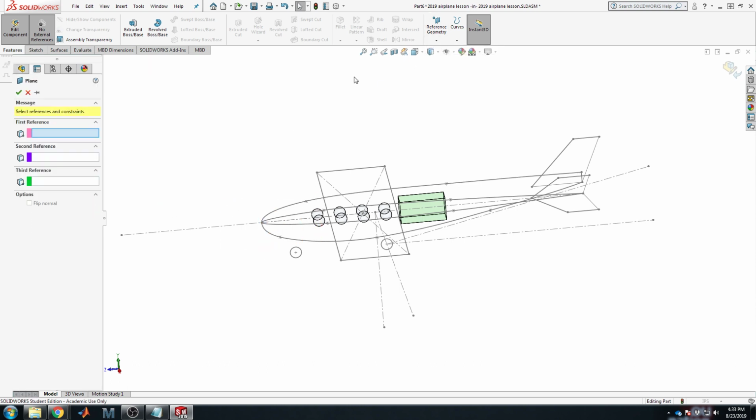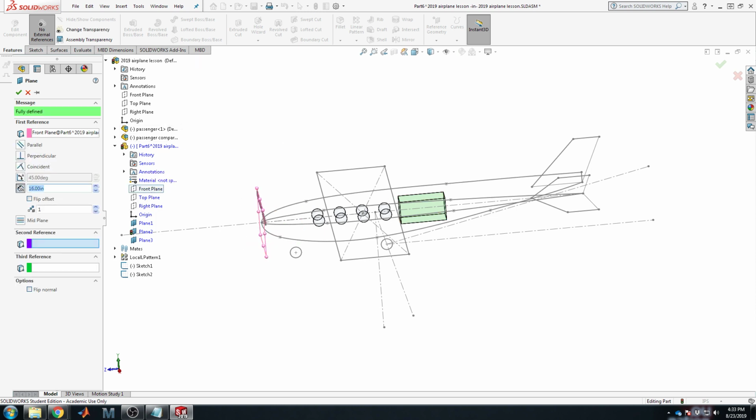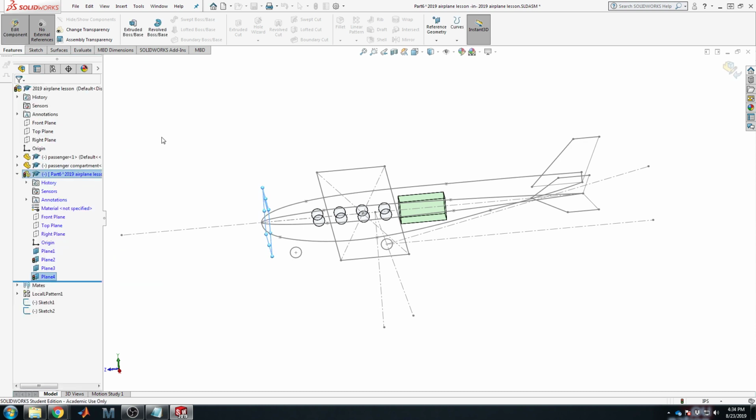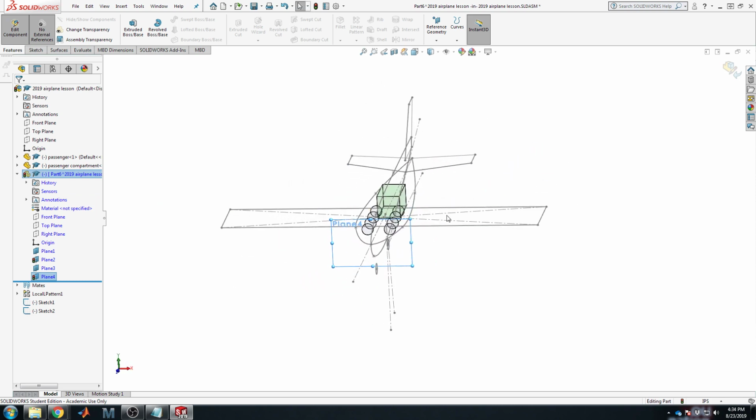And the last one to make, that maybe should have been the first, is related to the front. I want to go back maybe even just half an inch. And the reason for creating this will become apparent shortly. So this is where the advisement, maybe you heard in a previous video that you've watched here, that you're just drawing half the plane at a time, is going to become evident. We're just going to draw half the fuselage cross-section at each one of these major points.